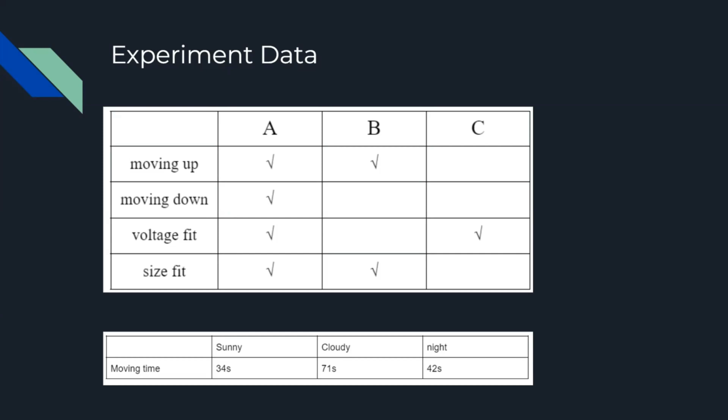The device temperature will increase fast because the voltage doesn't fit the Raspberry Pi, and it will be harmful to the motors and the Raspberry Pi. Also, in the experiment of type C, it provides less force to move the winches and shutter, and is quite small to fit in the whole system. So as a result, we eventually chose the reduction stepper motor for 5 VDC in my system.